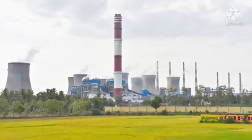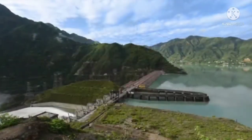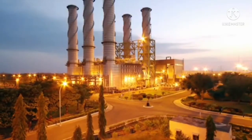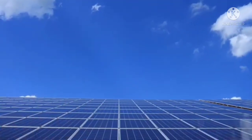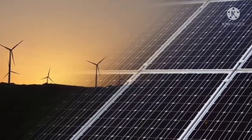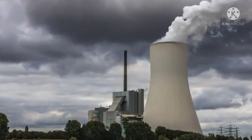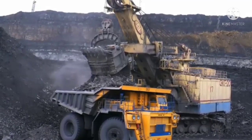The amount of energy consumed when an electrical appliance of power 1 kilowatt is used for 1 hour is called what? 1 kilowatt hour. Total energy consumed by an electrical appliance in kilowatt hour can be calculated by multiplying its power rating with the time duration in hours for which it was used. Then the cost of electrical energy will be the product of energy consumed in kilowatt hour with the rate in rupees per kilowatt hour. The consumption of electric energy can be calculated as power multiplied by time, divided by 1000. In this way we can calculate the electric energy we consume.